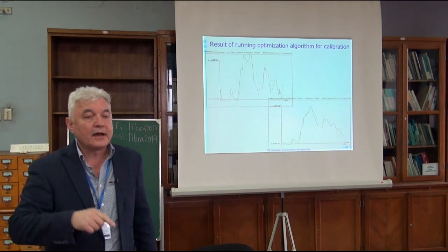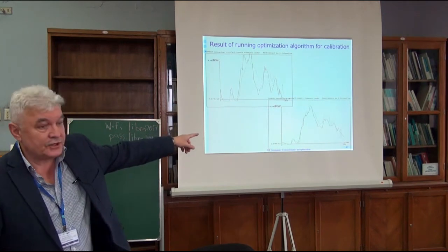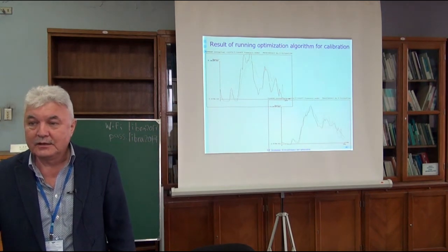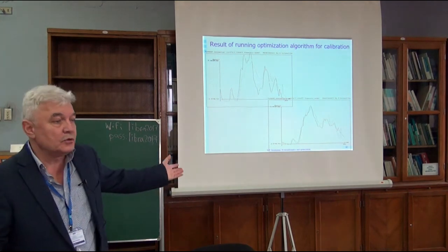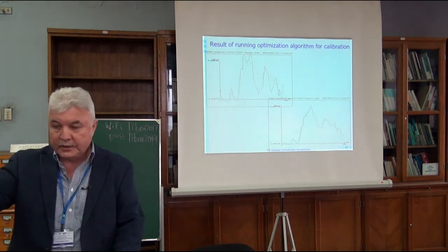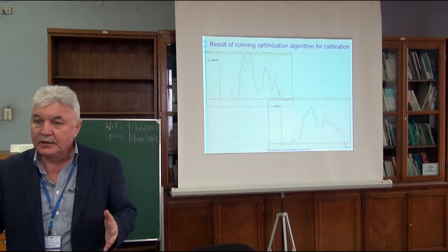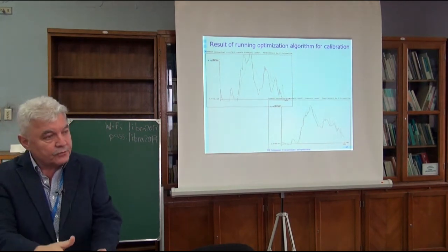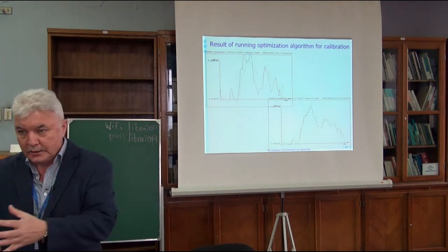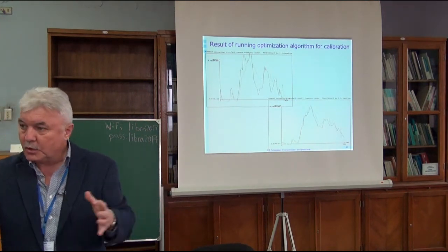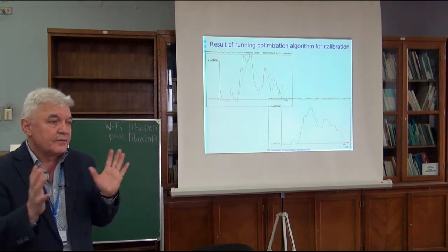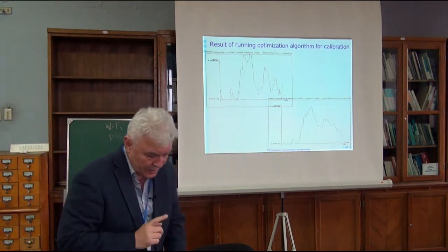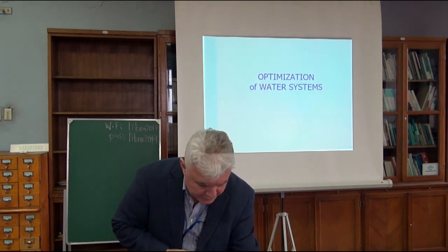But it would be unfair not to put floods here and to put very high flows in the test set. It's unfair because, of course, your model may not perform well on very extreme data. So fair is to split your data into blocks which would have enough low flows and high flows in each block, and then to train on one block and test on another block. That's the theory of modeling. But we'll talk about this on Wednesday. Good, let's move on because I have limited time, right?